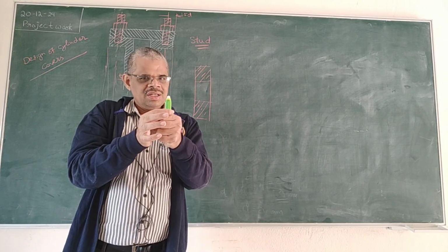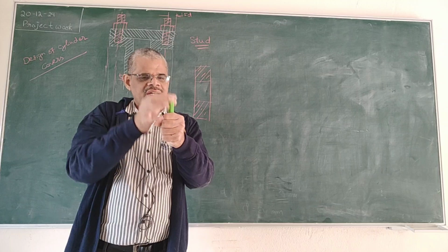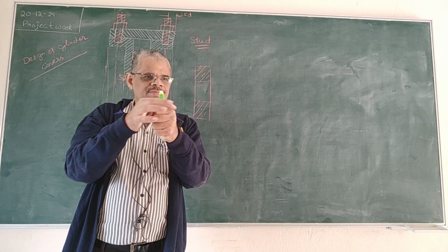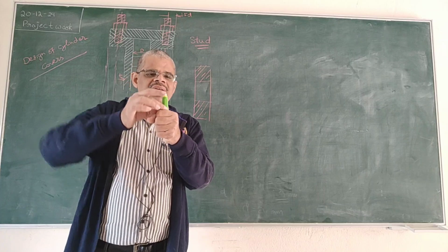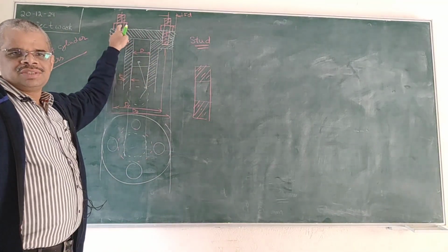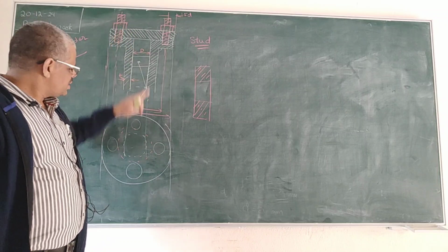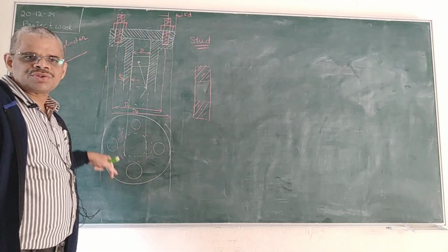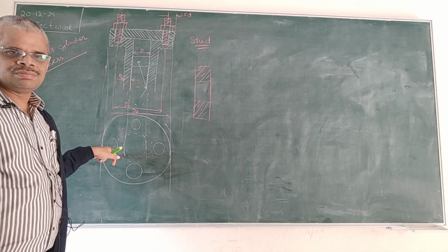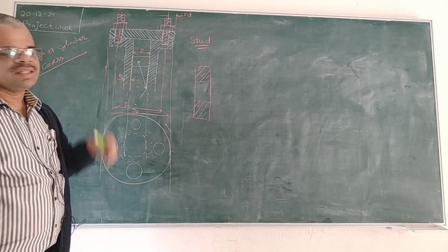So this is the cylindrical block, and this is the cap, cylinder head. Okay, both are joined with the help of the stud, and on the top a nut is inserted like this. Is it clear? So like that, there may be number of bolts. Here only I have shown 4 bolts, 4 studs. There may be number of studs. Okay, like this joint is